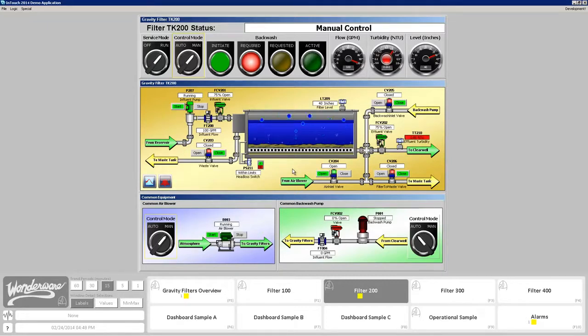What we find is that when people are looking at the screen, most of the time they're just looking at the bubbles because that movement is extremely distracting. Even though those bubbles don't require an action right now, that's where the operator's attention tends to center. So when you do things like spinning pumps or movement or blinking when things are not expected to be acted on, you are distracting your operator and you are reducing their situational awareness.